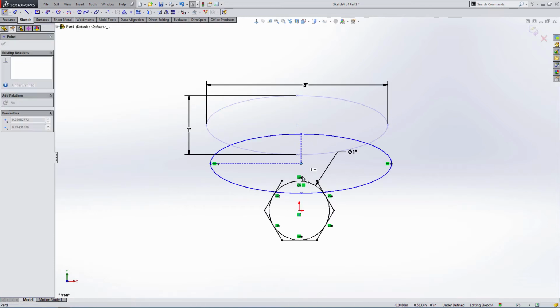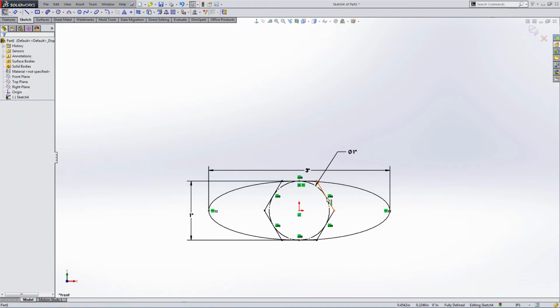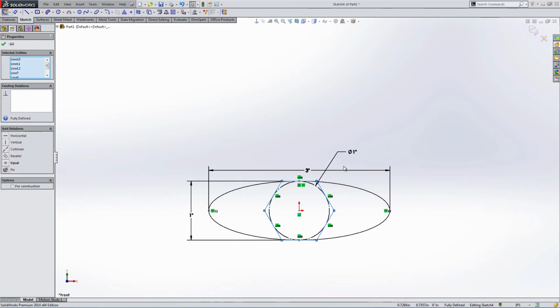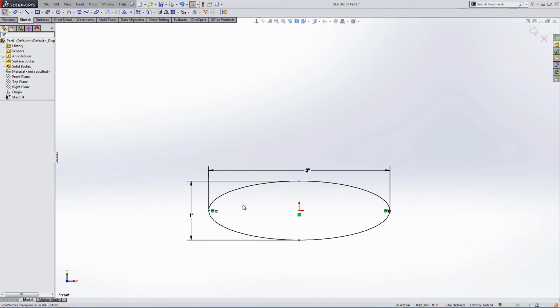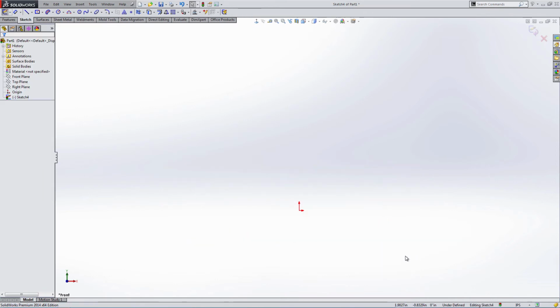And then we'll set this on the origin, get rid of this guy, select chain, delete. And so you can see it's fully constrained, this ellipse is. There's not a whole lot else I can think of right now. We'll cover splines and dimensioning between planes, and the other thing you can dimension between.